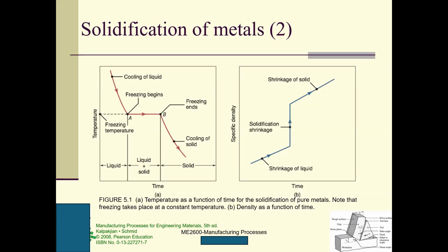Same thing here. Temperature is related to the heat, but when the temperature remains constant, there is still heat release. So this is the cooling, from liquid to liquid plus solid, and then fully solid. After this becomes fully solid, as the time goes, the temperature continues decreasing.